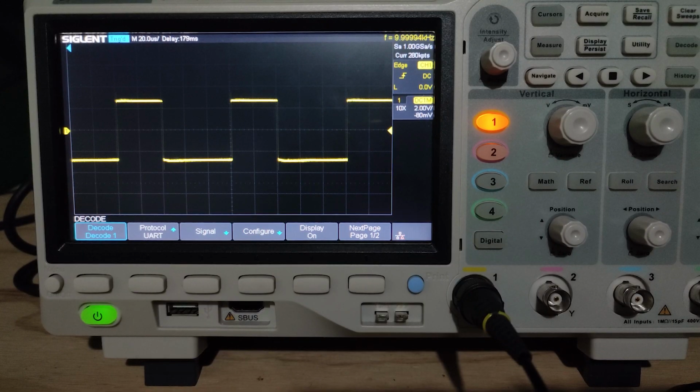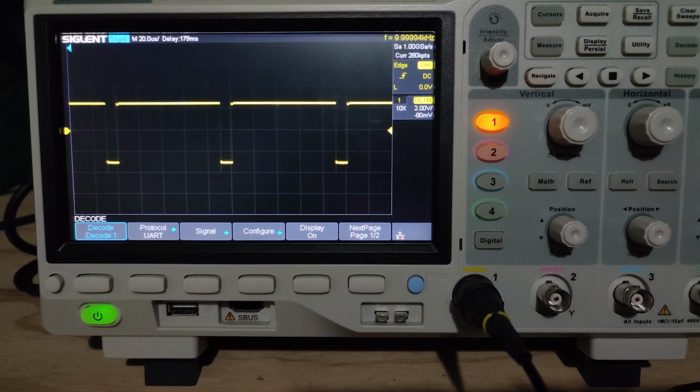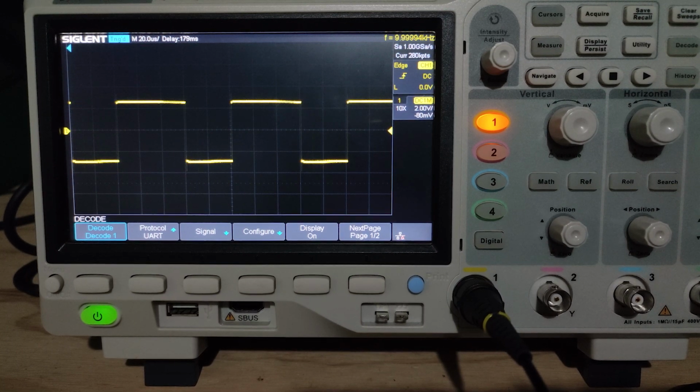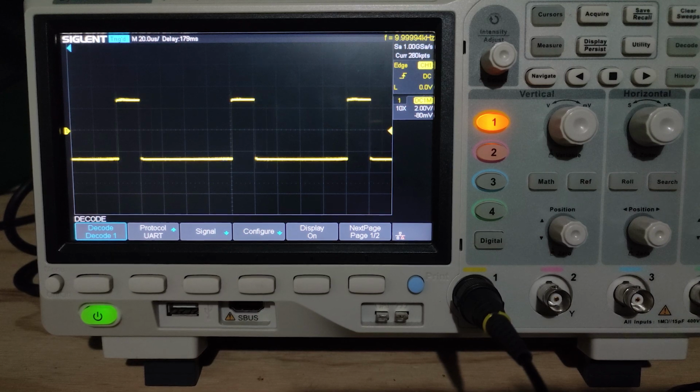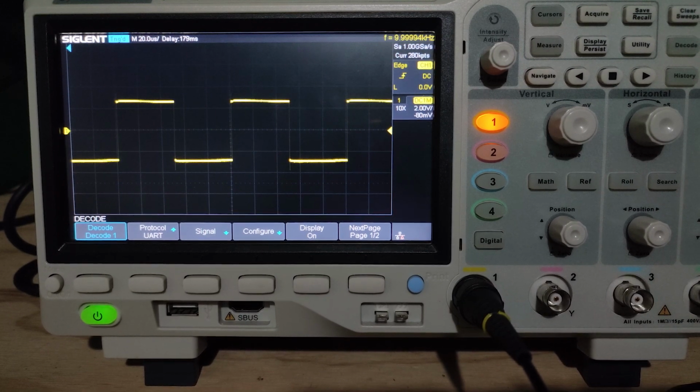We can see in this video the signal shown in the oscilloscope. We have a stable frequency of 10 kHz, but we can control the duty cycle of the signal with the controls of the function generator. We can see that we can go up to 100% and then go down to practically 0, or off state. This is obviously a digital method of generating PWM. We also have analog methods, but those will be seen further in the video.